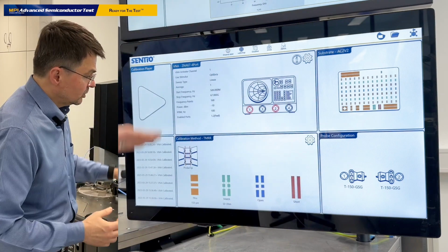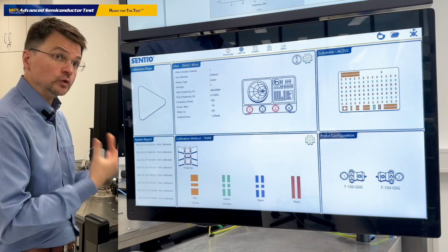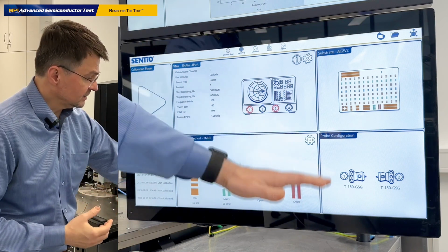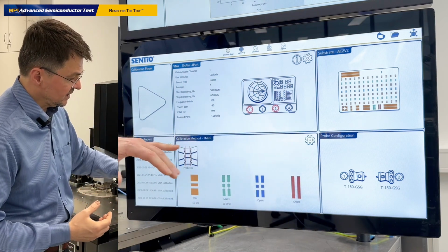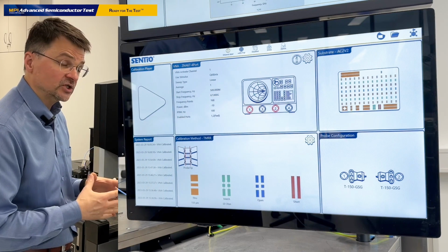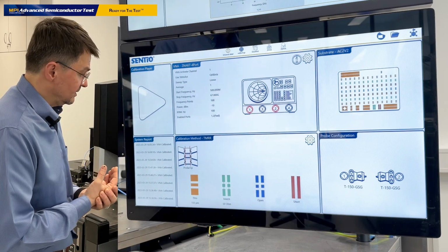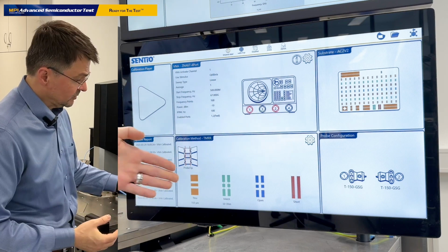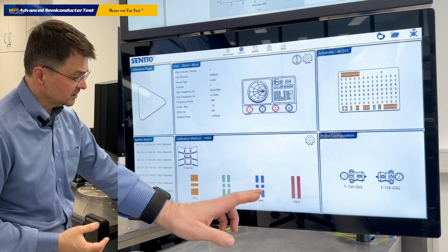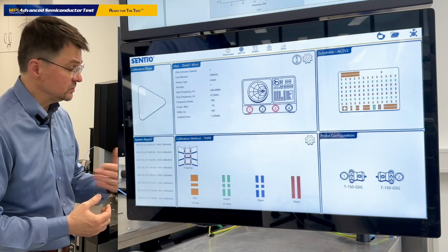And we can calibrate the system for the 2-port calibration procedures, and the default calibration method which is selected is through match reflect. This is an advanced calibration algorithm developed by MPI engineers. And it requires a through standard, the load standard, the open standard, and the short standard measured during the calibration process.